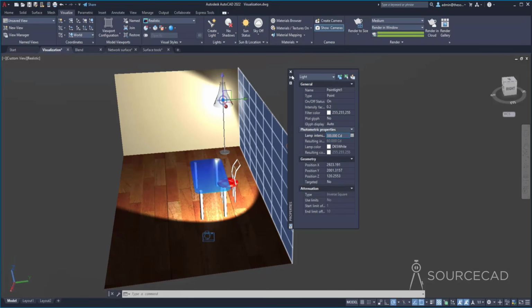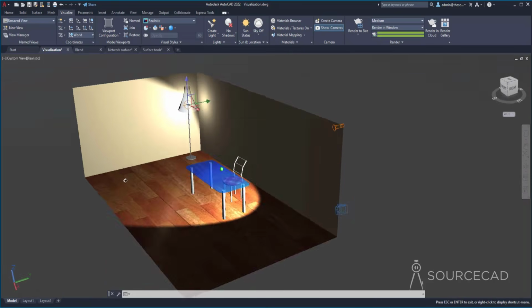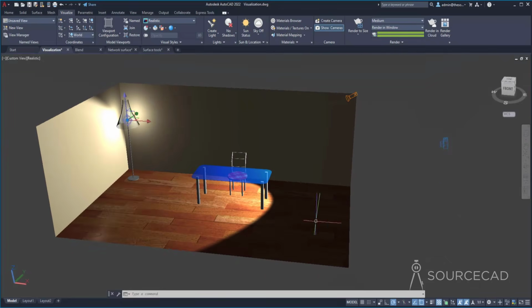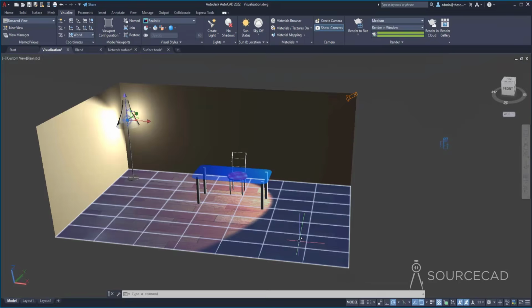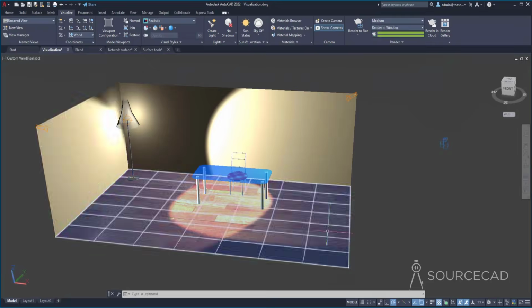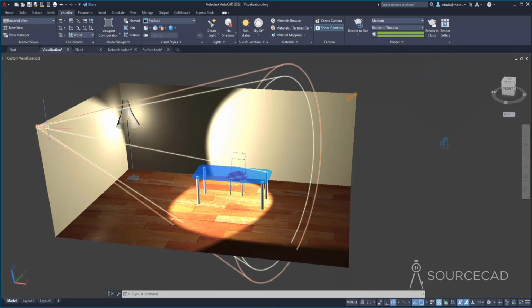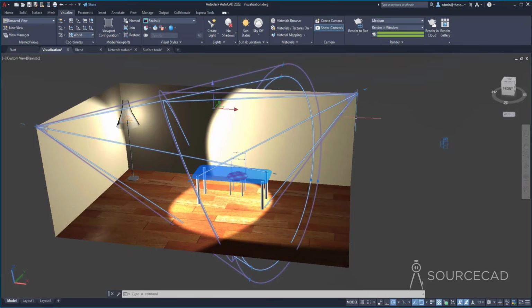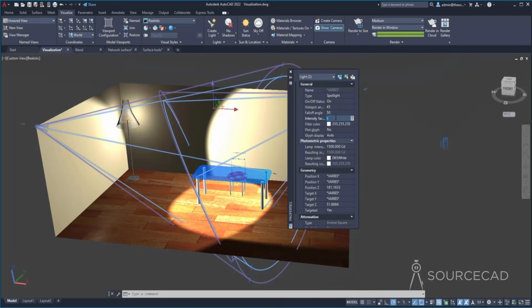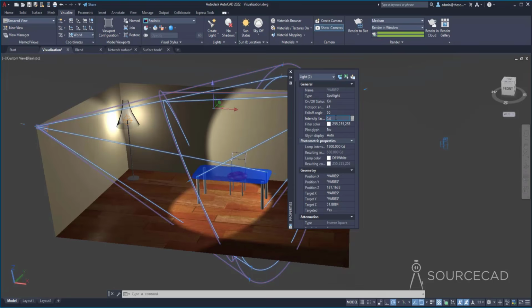So with this intensity, I think the table light is fixed, but we still have this very intense spotlight. Well, I think we should add one from this side too, just to fill this gap. So I'll go to this spotlight, I'll select this part here, and I'll just drop it right here and enter. There we are, we've got this thing filled. But once again, intensity is just too bright, so I'll select both of these spotlights, right click, and go to properties, and here let's change the intensity factor. I'll make it 0.4 this time, and also the intensity of lamp, I'll make it 500.